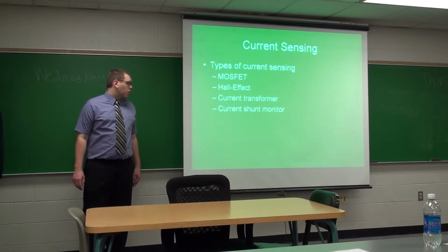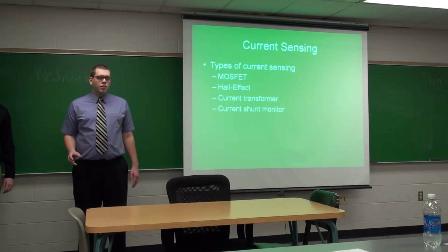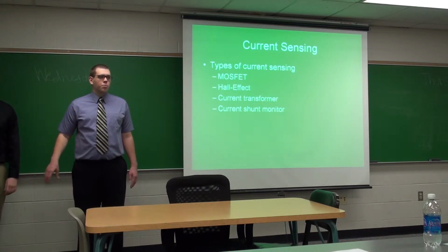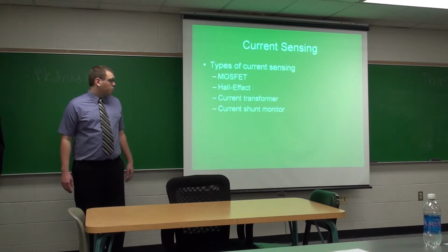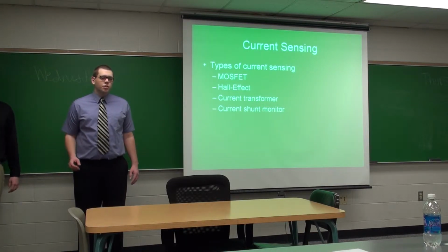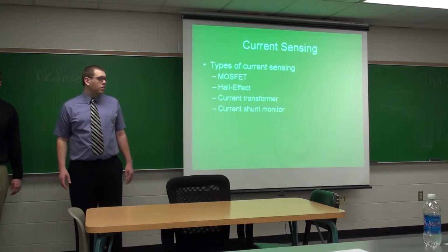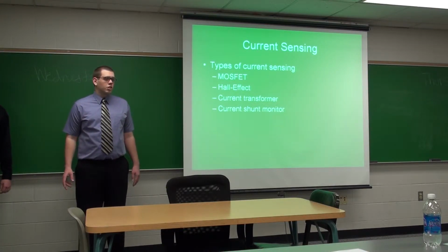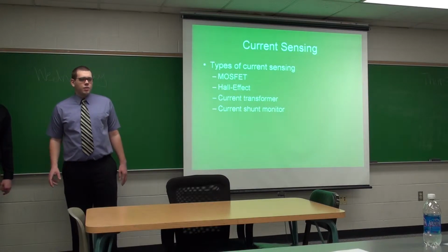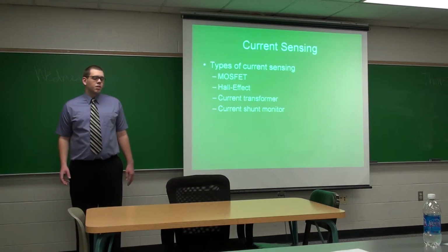And then our final idea was current shunt monitors, in which you have a current shunt resistor that a monitor looks at for the drop across it, and once it outputs a certain voltage for the drop, you just have to compare it. For that, we have low side and high side current shunt monitors. In the low side you have the resistor from source to ground, but in order to use that, we would need a current transformer to isolate the current, and so we went with the high side current sensing, in which you have a resistor from the source to the load. And although there's a bit of an insertion loss, it is small when you use a really small resistance.